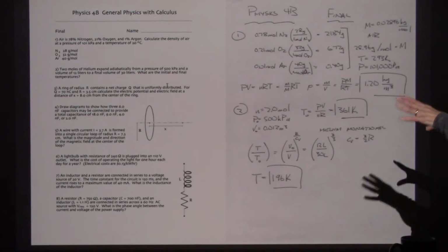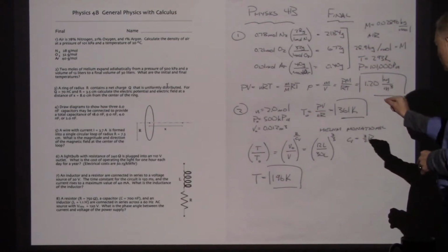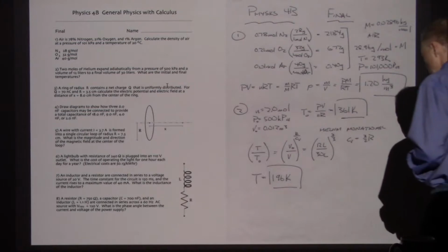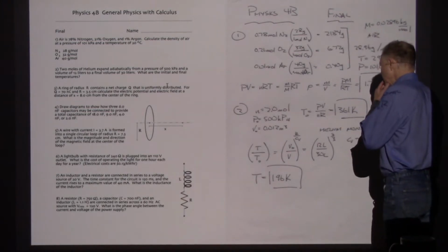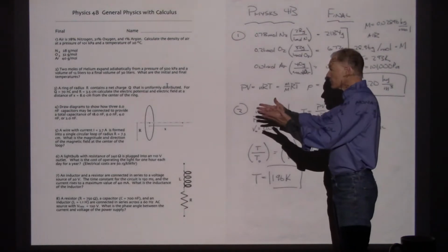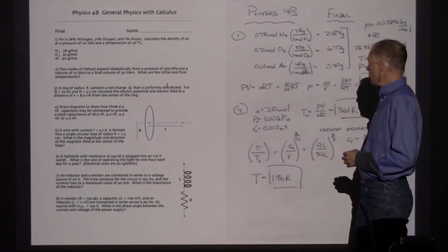So if I diagram this out as a PV diagram, the sample is going to follow an adiabatic path as it expands. Let's see what we've got here. I didn't include the pressures. It turns out there was enough to solve the problem just from working from the volumes before and after.